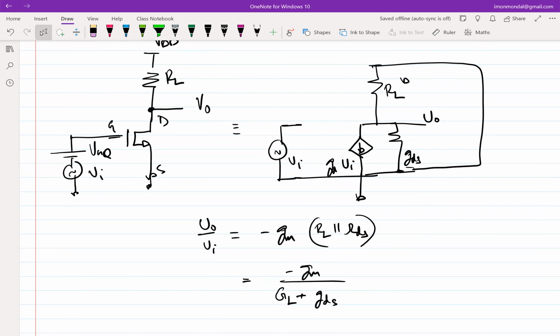but there is a profound effect of this GDS. And the profound effect is the following. In the common source amplifier question that you had done till now, what you had assumed is if I have infinite VDD available to me, you could have gotten an infinite gain, right? So you keep on increasing RL, for the same GM, and my gain was GM times RL. If I keep increasing RL, the drop across RL will increase, and to accommodate that drop, I have to increase VDD. But in principle, in theory, I could have gotten infinite gain by playing that game.